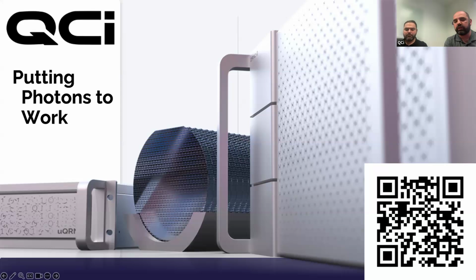As far as the validation steps, we do the standard ellipsometry and white light interferometry to characterize the uniformity and TTV of the wafers. Especially when it comes to PPLN, the height variation of the waveguide is very important. So at the moment, we're developing techniques to scan the PPLN waveguides to understand what the TTV looks like and use that to inform our designs. We're also developing technology for in situ monitoring of poling to improve the yield of that fabrication process.